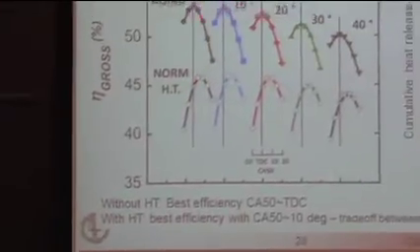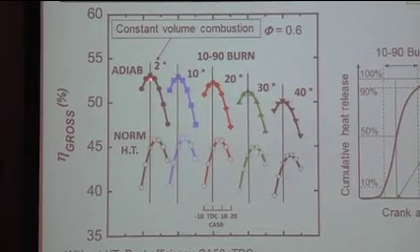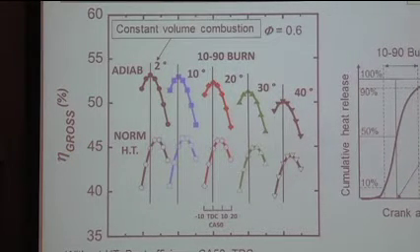If you can keep the gases cool, you obviously reduce the heat losses, so that would be what would happen if you went past top dead center. But if you wait too late, then you lose some of the pressure, the PDV work, so there's that compromise. Other thing to note, this difference here is on the order of 10% on this plot, or 8% or something. So that represents quite a big change in fuel efficiency because of the loss to the coolant, essentially.